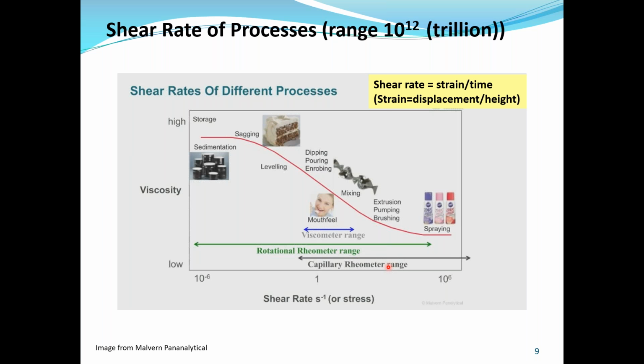And what are the must-have capabilities? Again, it depends on the question you're trying to answer. Any rheometer will give you the rotational and the oscillational capabilities. I would make sure that you have a good array of geometries in terms of plates and cones.